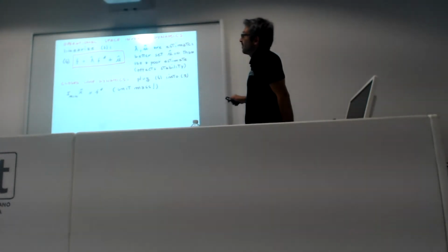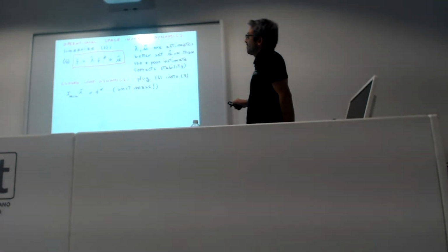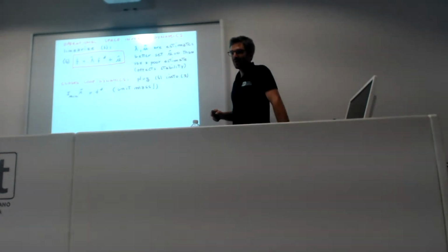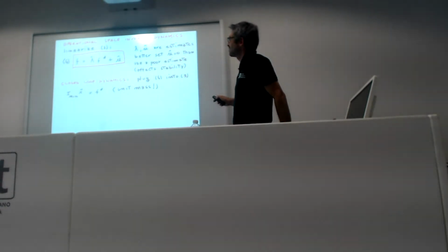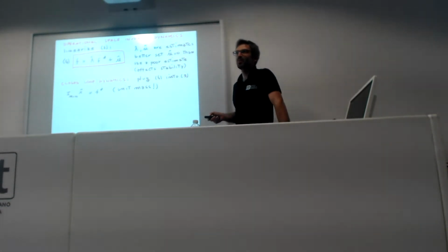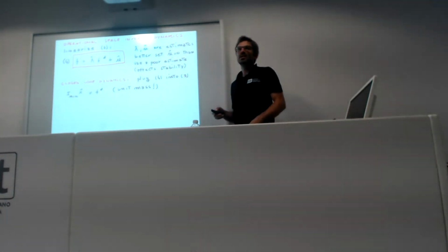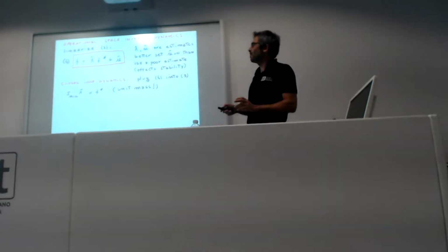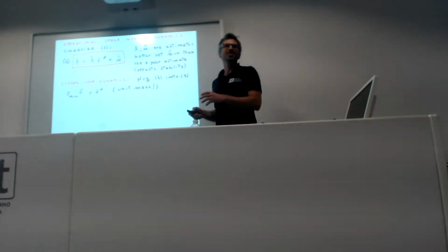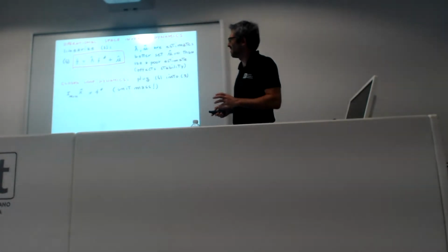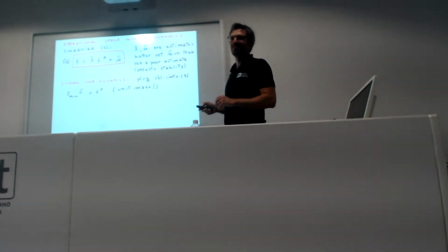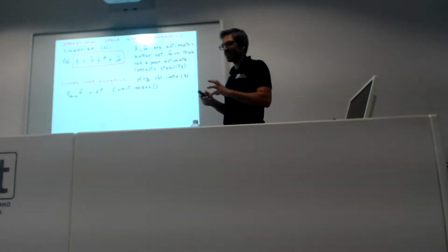But in the case of mu, if you don't have a good estimate, it's better to set it to 0, because mu will act as a positive damping, so it can have a destabilizing effect if you have a poor estimate, and then it can affect stability. That's the reason for which people don't implement operational space inverse dynamics, because it's very sensitive to this problem.